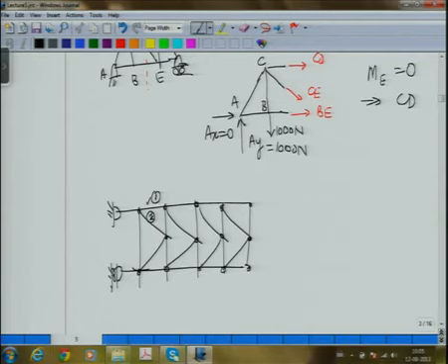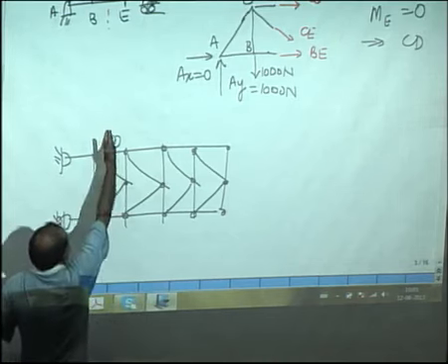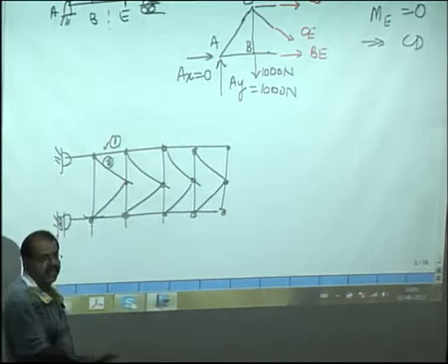Well, obviously one guideline is that your section has to be such that the forces which you want to find are exposed in the section. Otherwise, there is no point. So now if you have to find forces in 1 and 2, you have to make a cut where these two are exposed.